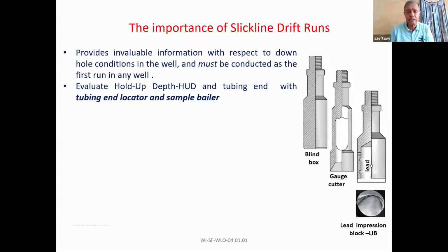Category 0 means your wellhead pressure is 0. What is the minimum pressure rating of the pressure control equipment? 3000 psi. Although the wellhead pressure is 0, 3000 psi is a must.